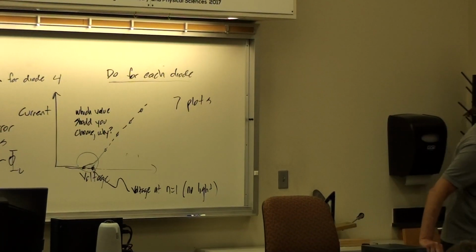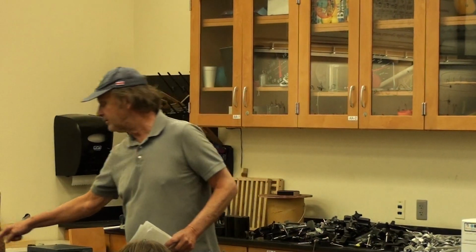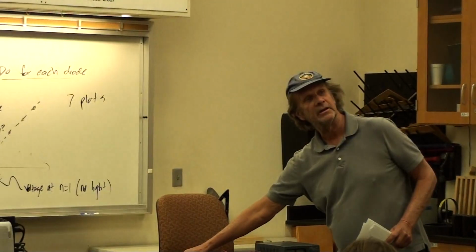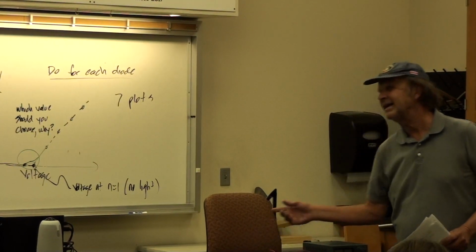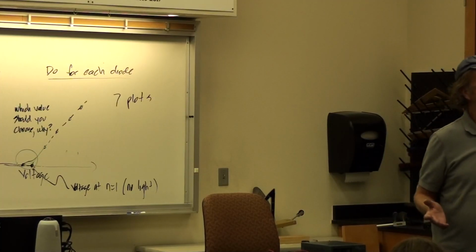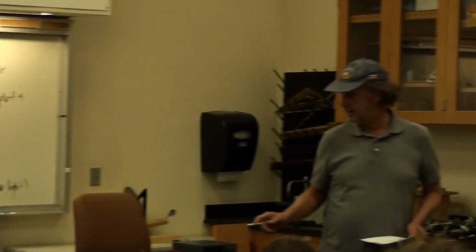At least this lab should be relatively easy to collect the data. And so just try to be careful. And remember, when the light goes out, that's when you really start looking at the microamps over here. And then you back off just a little more, because you might have maybe 2 or 1 microamp when this thing looks like it's going out.